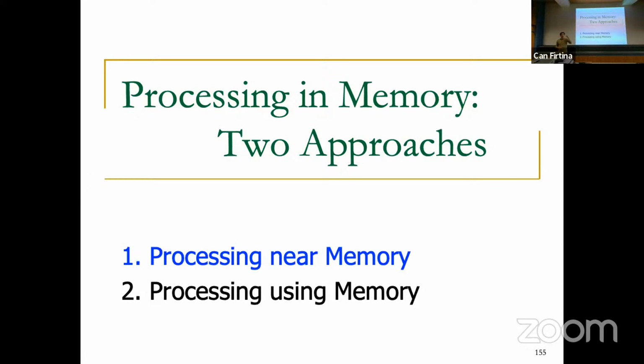What happens if you activate at the same time more than one row? In each bit line, you're going to activate either 2 cells or 3 cells or 4 cells, or assuming that you can randomly choose the number you want, right? But let's say we activate 3 rows at the same time. What are the possible contents of these 3 rows? In total, they have 8 possible variations of contents, right? Let's think, for example, about 2 1s and 1 0. What do you think that the sense amplifier is going to read if I have 2 1s and 1 0?